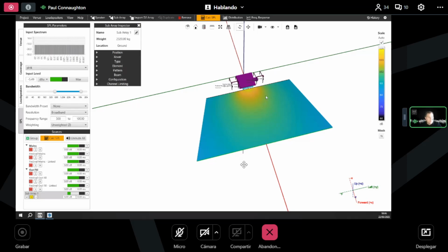So what we need to do before we start our calculations is make sure our SPL settings are correct. This is again what we were talking about earlier, where we can map SPL based on a fixed maximum level, or alternatively using auto by setting the decibel range you wish to include in the calculation.